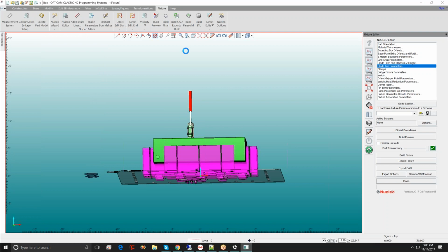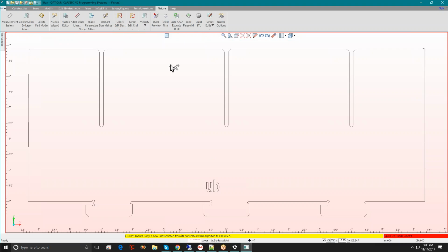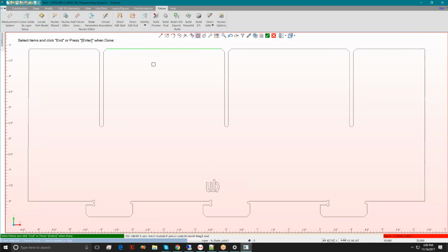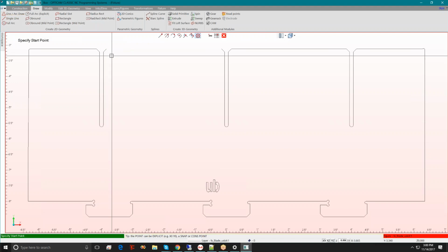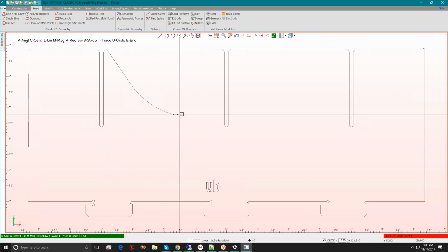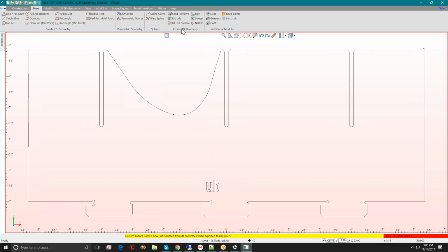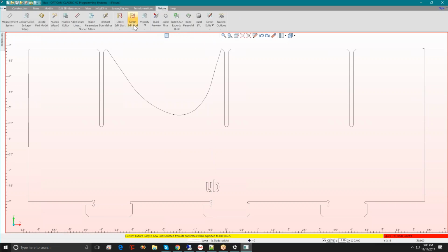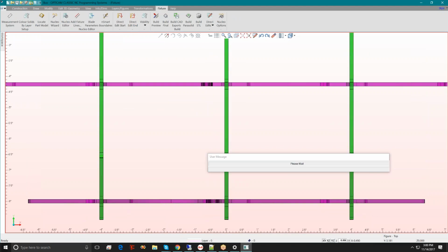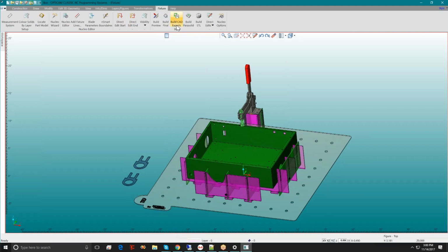What you can do though after the fact is direct edit it. I'll show you that. So direct edit, and then it says pick the solid body. I'll pick this one because you can see it easier. And I can do stuff like remove this line. I can then draw with line art. I'm in automatic snap mode, end of, arc mode, A for arc. Make sure my geometry is closed, and if I go fixture, end, direct edit, end. Okay, I got that in there then, and then I could export that again to my CAD system. I could just export it, and it'll have that in it.